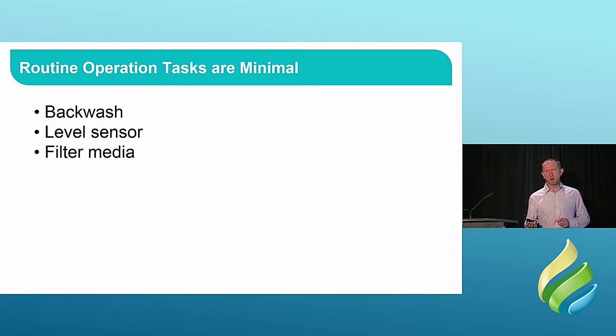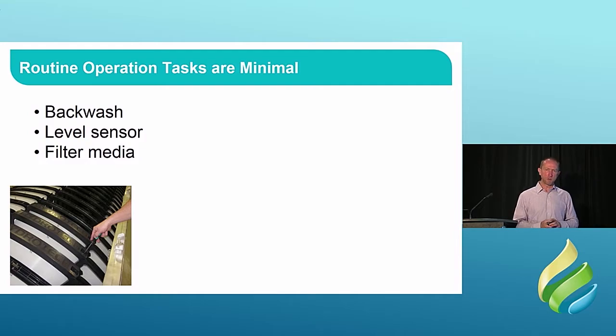You might need to do a little bit of maintenance on the level sensor. If you've got a float, then maybe give a little spray clean, get the sludge off it from time to time. Ultrasonics, keep them clean, that kind of stuff. And sooner or later, you are going to have to replace filter media. As I said earlier, these things last a very long time, but sooner or later it's going to fail. So have a look at that, inspect it. If you do need to replace filter media, you're going to see that because it's going to get torn, basically. It's going to get worn out, and then it's going to tear.